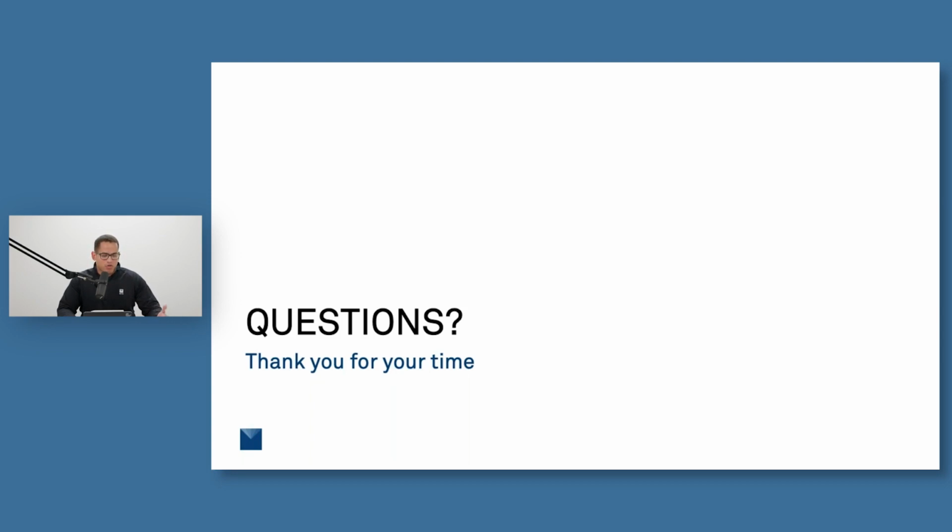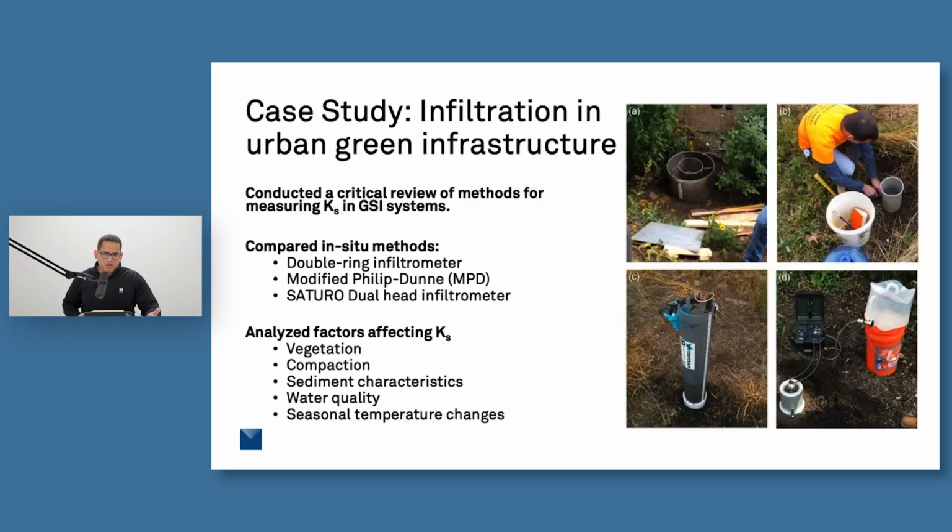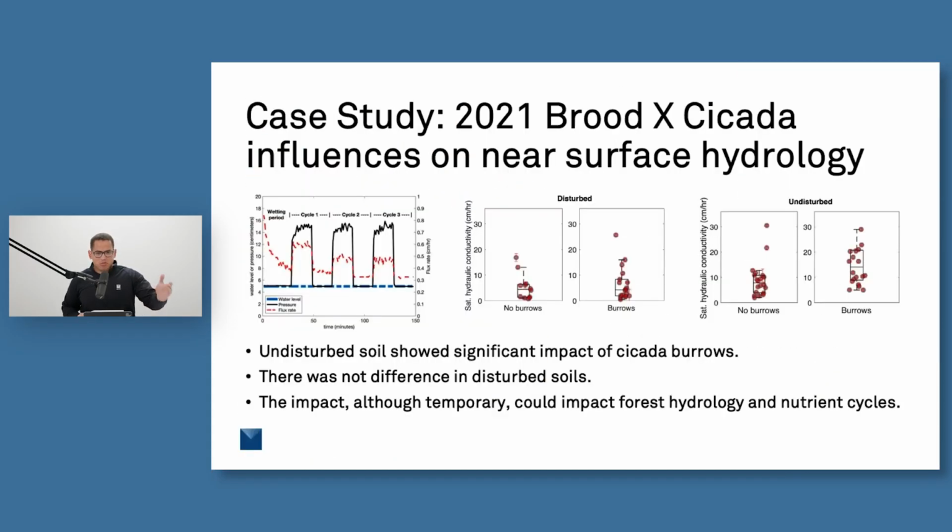But of course, when we're making hydraulic conductivity measurements, and you saw one of those examples, actually, I'll just go back to it really quick. You can see what happens as we're infiltrating water in the unsaturated conditions. Initially, the infiltration rate is higher, and then as the soil in our measurement area becomes saturated, you see that measurement plateaus or reaches what we call a quasi-steady state, and ultimately that steady state value is what we're using to get our hydraulic conductivity value.